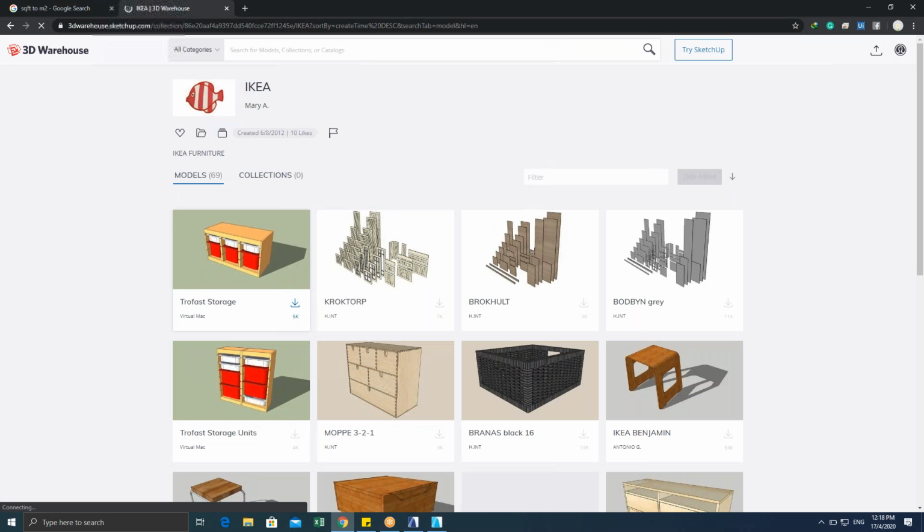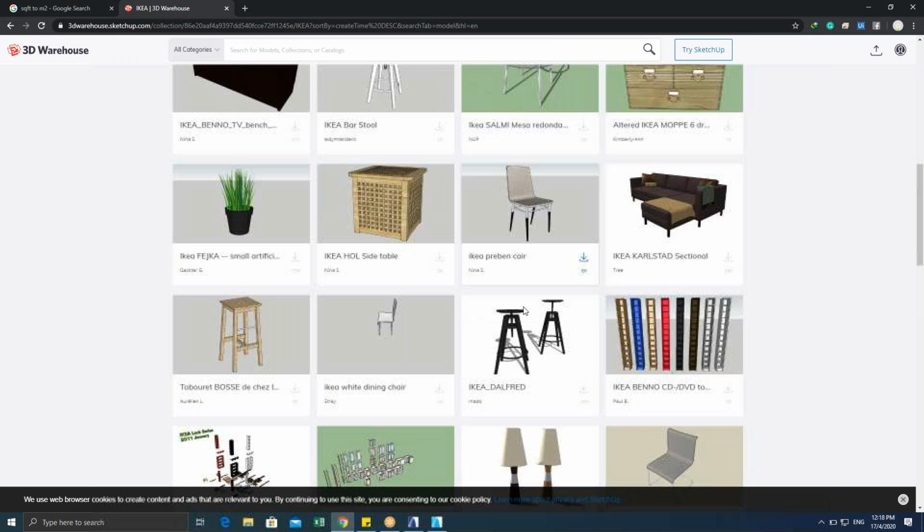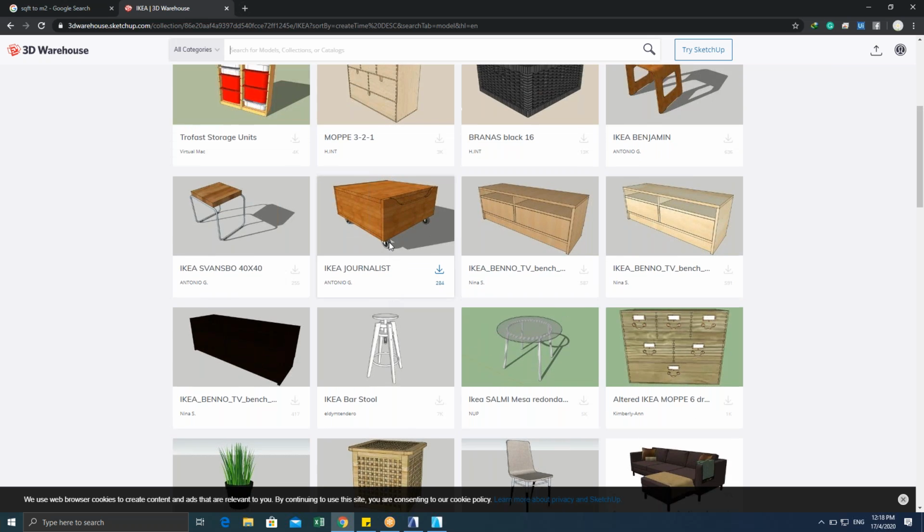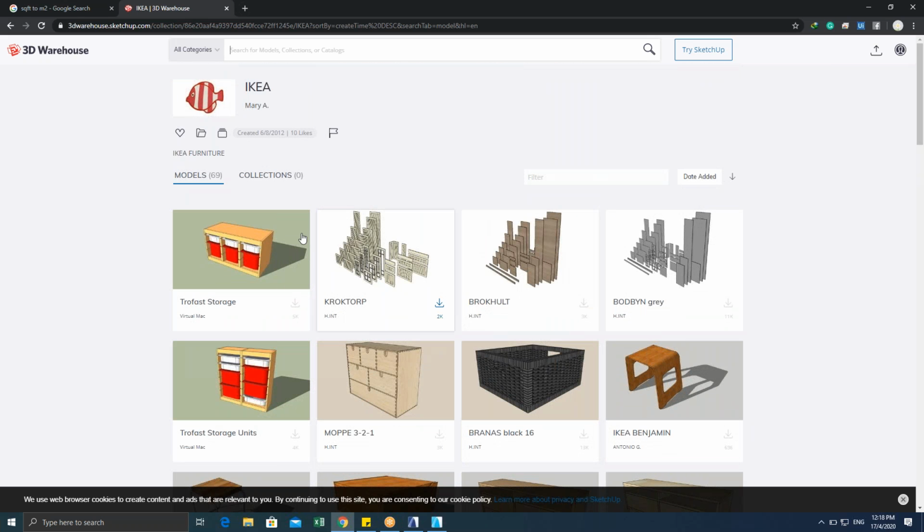You see, sometimes in 3D Warehouse also, but you must make sure before you download. You can download like that too, just download and drag into ARCHICAD. You can do like that. But make sure before you drag, because sometimes in this SketchUp file, they have a lot of ghosts, unnecessary things inside there. Make sure you purge and clean first before you put it into ARCHICAD. If not, sometimes it can make your file bigger because of a lot of unnecessary things inside there.